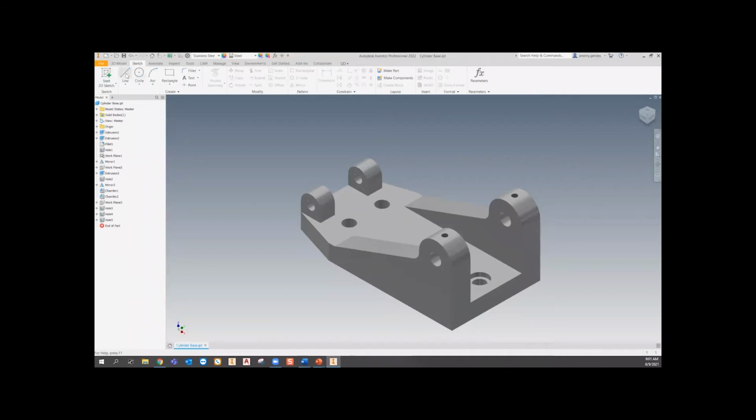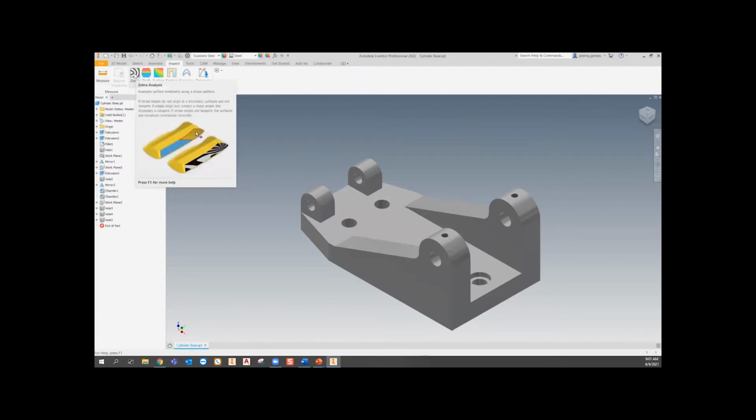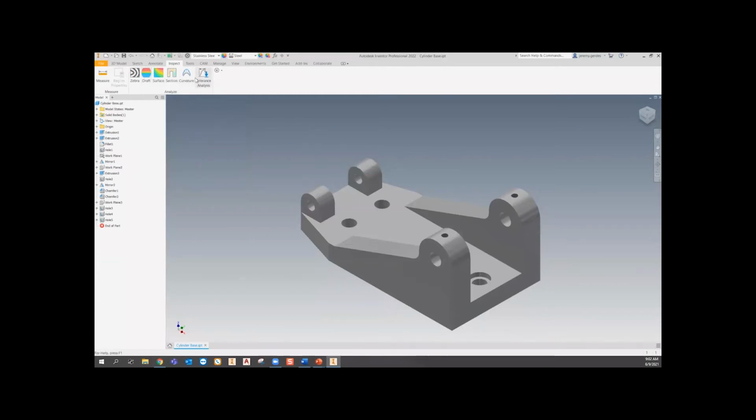So then on your sketch tab, you have lines, circles, all the different basic sketch commands. Then annotate, you can do 3D annotations on a 3D model. Inspect, measure, you can give the surface a different pattern if you have a complex shape that you don't know exactly, or sometimes on a 2D monitor it's hard to see particular 3D geometry. So sometimes adding some of these will let you see where the curves are a little bit easier.